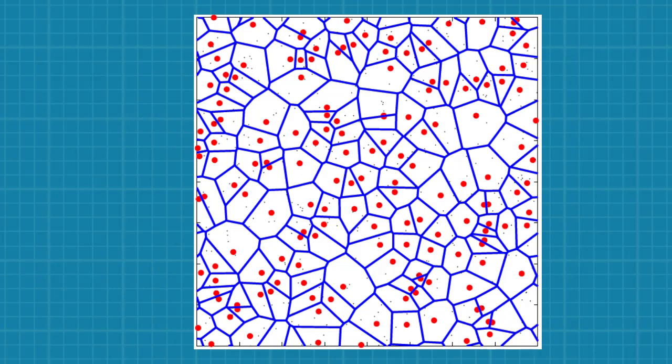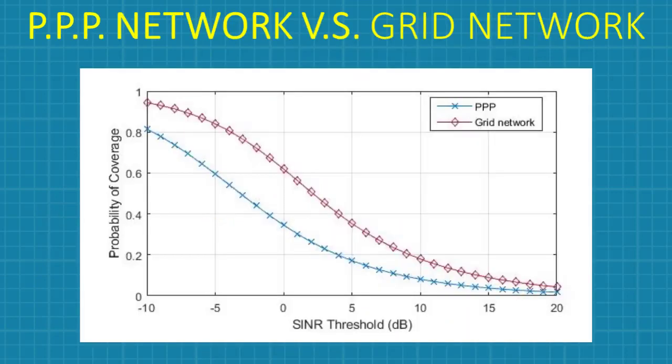In the PPP model, the distance between UAVs is randomly placed, so both the serving and interfering UAV can be close to the user, which results in more interference power than the real network. Therefore, the PPP model gives pessimistic results due to the strong interference generated by nearby UAVs. On the other hand, the grid model is optimistic, because the actual UAV networks always show a certain degree of irregularity.